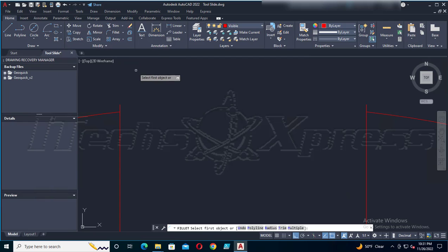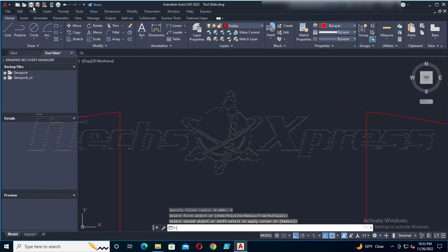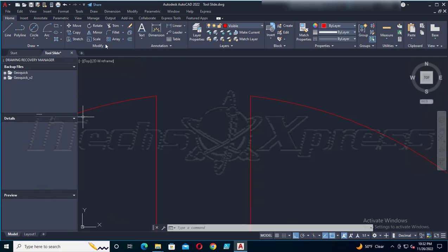however, if I go to the fillet option and select this line and then select this line, it automatically fillets that, and then I can do the same thing here. Actually, I said type in radius for R 0, and now select first line and second line, and it takes care of that for me. And I'll save.